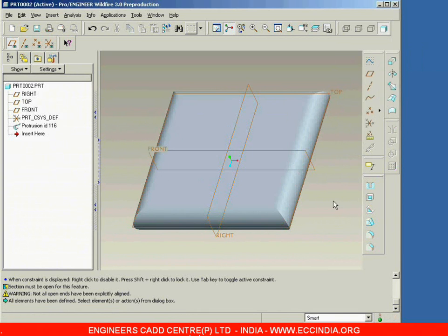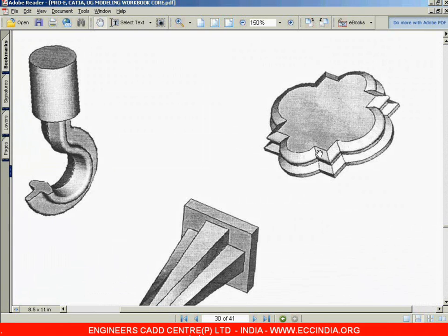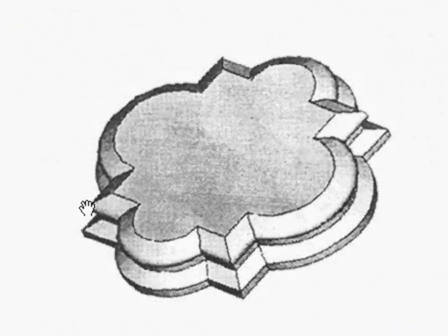And again this concept can be used on a workbook figure. So this is the workbook figure. On this figure you can use this sweep closed trajectory. So you can get the trajectory from the top view, and then you have to draw the section. Sections are nothing but these inclined lines. Draw them and see the result.